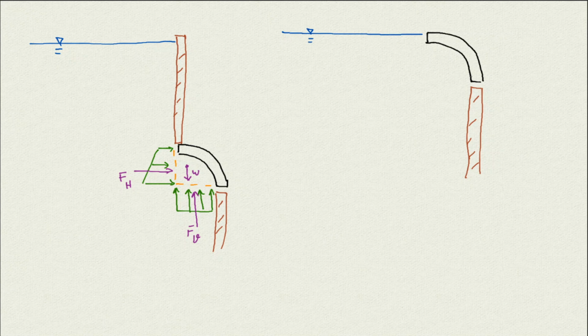So again, this time the water is underneath the plate, and there is nothing above the plate, unlike the previous one. So the same as before, we go ahead and draw the vertical and horizontal line, and then we put the pressure on them. Again, because here it is at the water surface, the pressure starts from 0 and increases linearly until you get to this point. So we have a triangle instead of a trapezoid. And then we will have this one also.